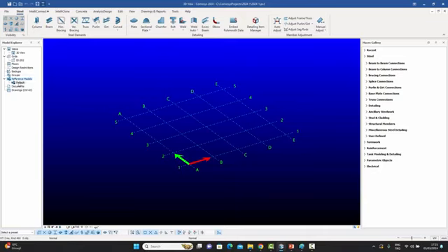Let's just click on the default subgroup and right click. We see that in the options we have add an IFC model or add a DXF model. You can see them over here. These are the two types of reference models which are supported at this moment in COMOSYS. Obviously, the most used one will be the IFC model, but you can also import DXF models.